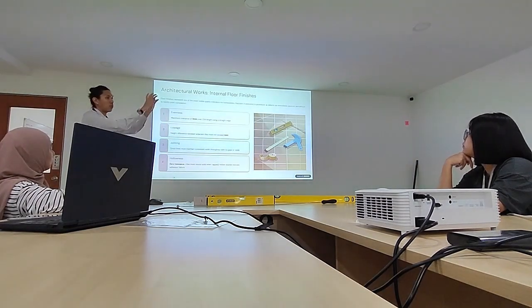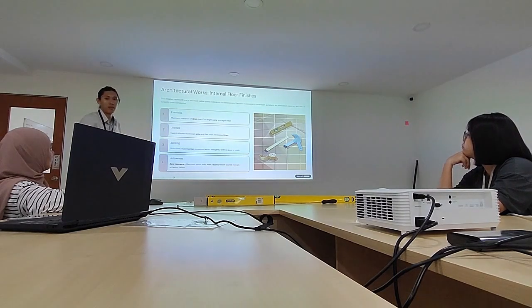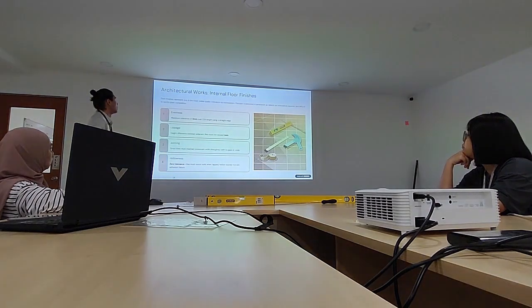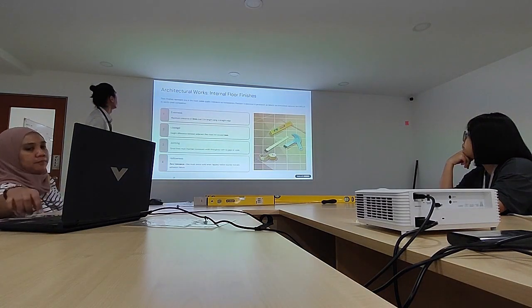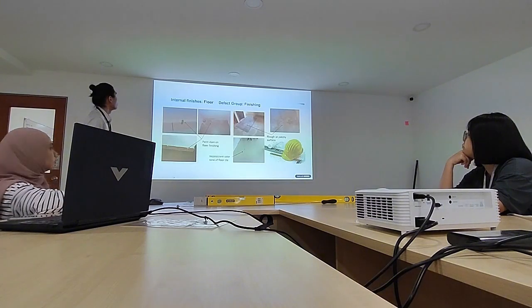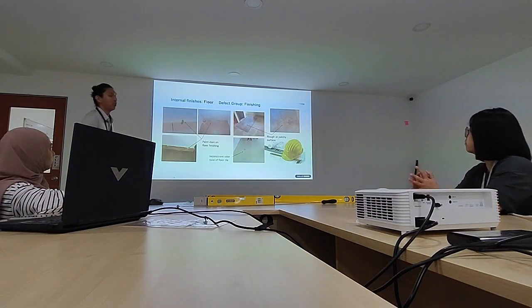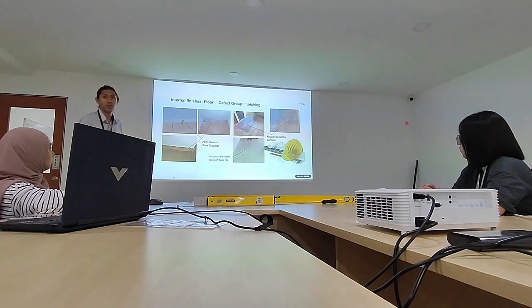And also lastly, tolerance, we got 0 tolerance. This is for the mosaic, how many points you can get for the scoring panel. So the tolerance is 0 tolerance no matter on the plaster, floor tiles, or also the wall tiles. Everything is 0 tolerance. Okay, next. So these are the items that we will check during the QRC inspection.